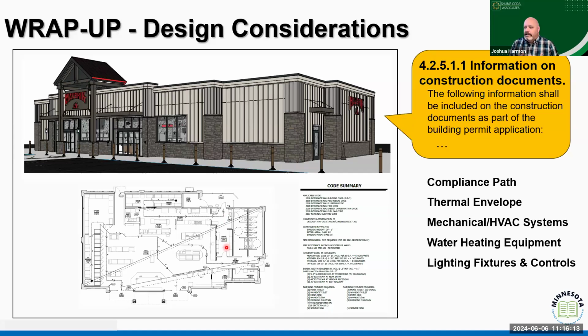The corridor is a semi-heated space, but above that semi-heated space is the HVAC system, the ductwork, and that ductwork has to be treated differently because it's in a semi-heated space versus being part of the conditioned area, completely within the building thermal envelope.